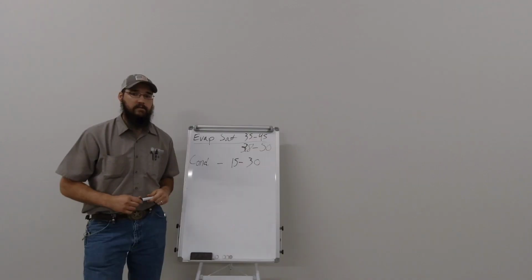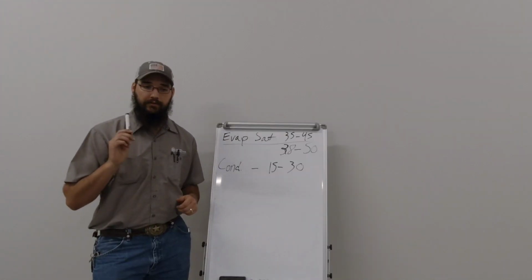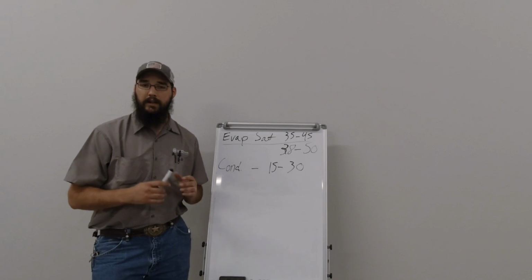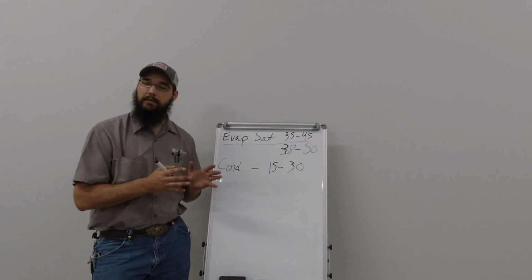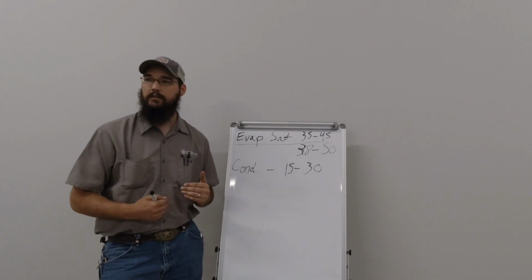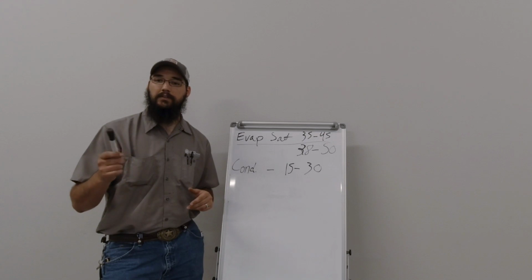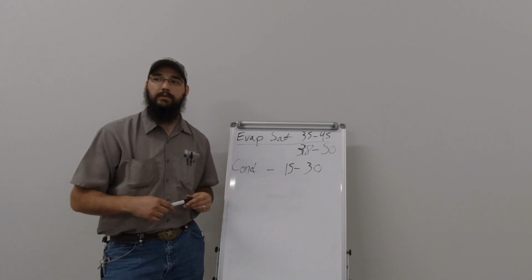Does humidity affect the condenser load, like the amount? No, it does not affect the condenser, specifically the outdoor coil. In that case, because the condenser is only worried about a sensible temperature, it is not worried about a latent load. I was just wondering because they always had the wet bulb travel on the charging charts of the old systems. On the old systems, because they charge via superheat on the indoor coil most of the time.